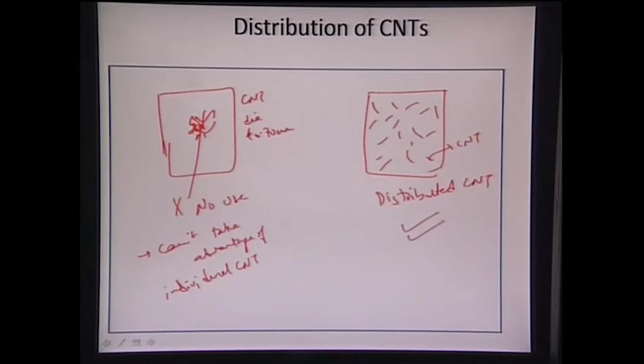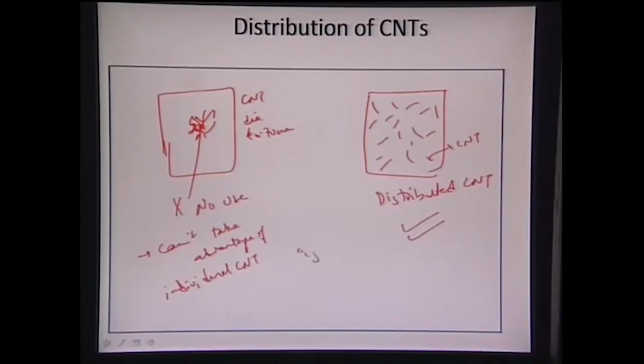Owing to the very high surface area of carbon nanotubes, they tend to agglomerate. So that agglomeration has to be avoided in the first stage itself, that is the blending of powder. If you are utilizing a powder which serves as a feedstock for plasma spraying, the agglomeration has to be avoided in the blending stage itself, where we take powders of hydroxyapatite and mix them with CNTs. CNTs should get dispersed in the powder formation itself. So in the powder feedstock, we should have dispersed CNTs in the matrix.